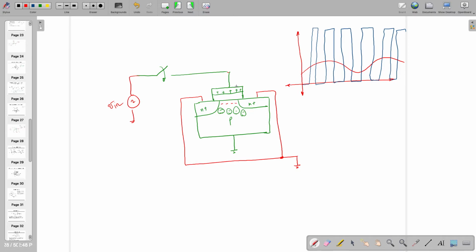So what I'm going to observe here, when it's on, input charge is equal to V in times the value of capacitance. So how much is the value of capacitance? Somebody told the correct answer, C ox, right? C is equivalent to W times L times C ox.